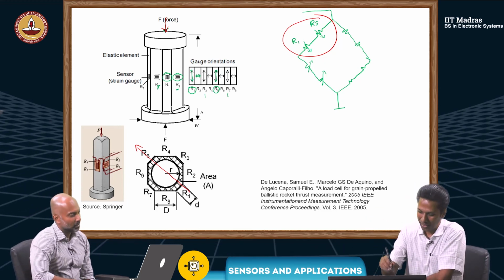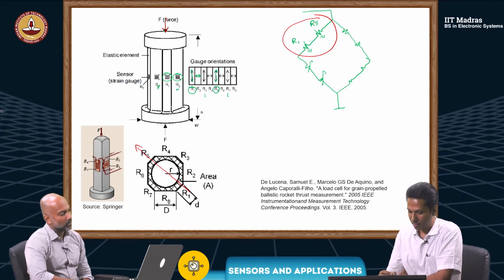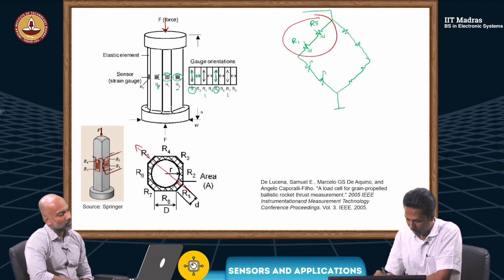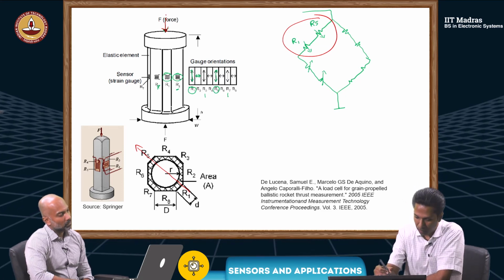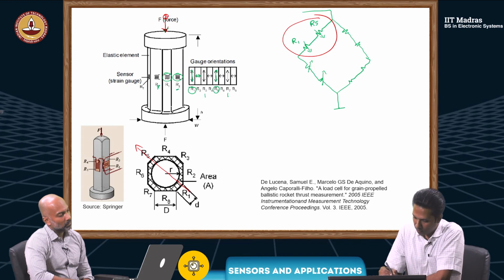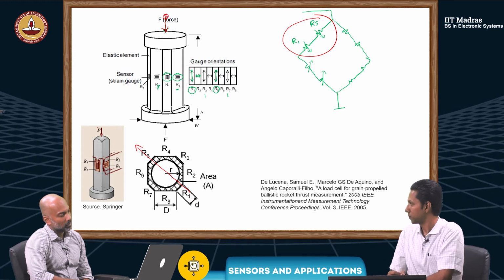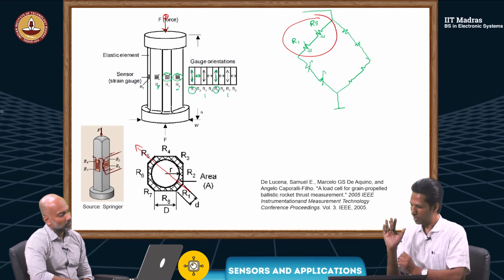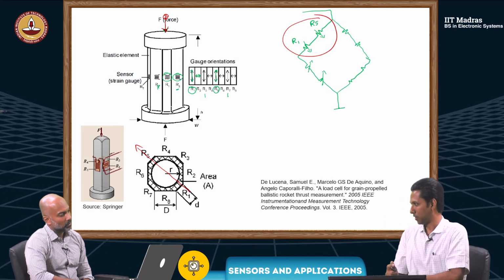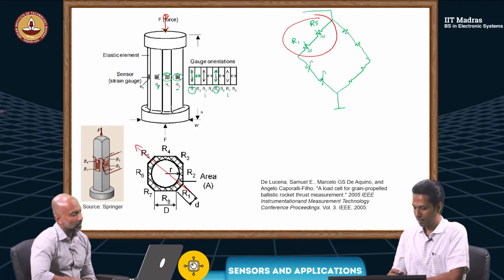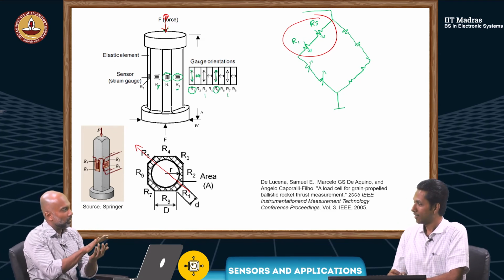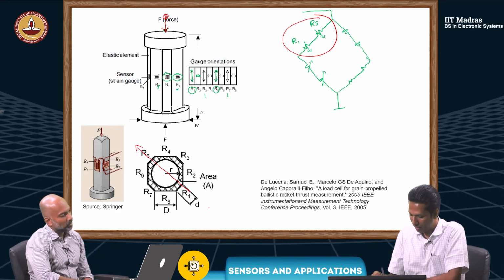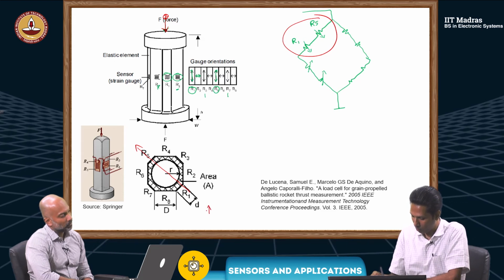It's difficult to draw. So that is there, right? Or the way I have drawn, it is into the plane because it's going towards upper, right? So what will happen? There will be a small bend towards R5. Yes. So then R1 will kind of elongate. Yeah, exactly. So R1 will have an increase in resistance.